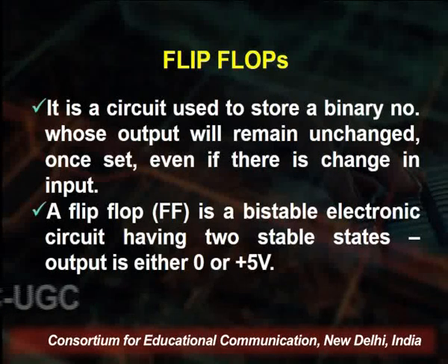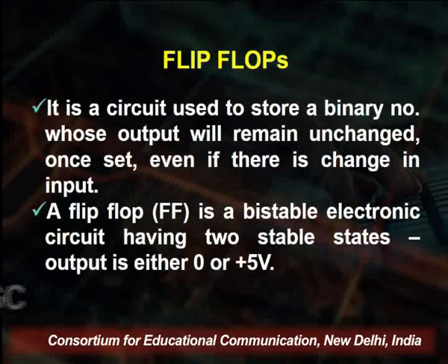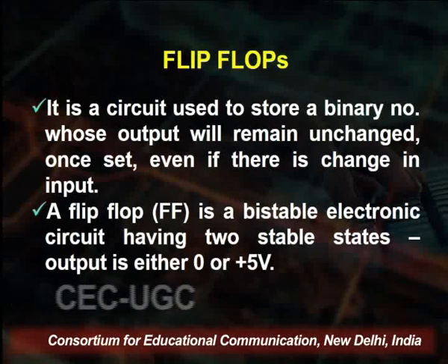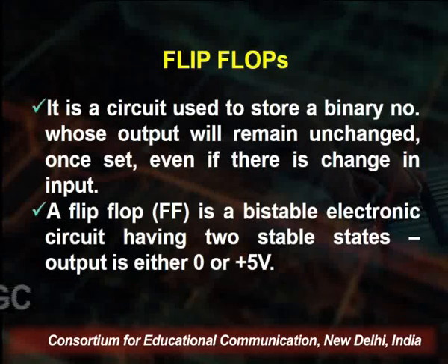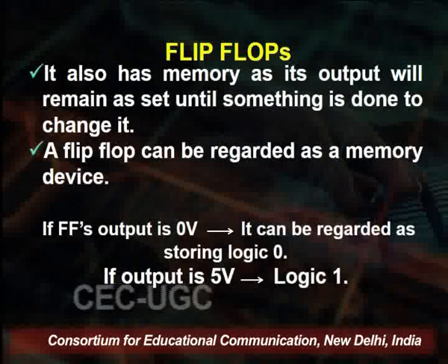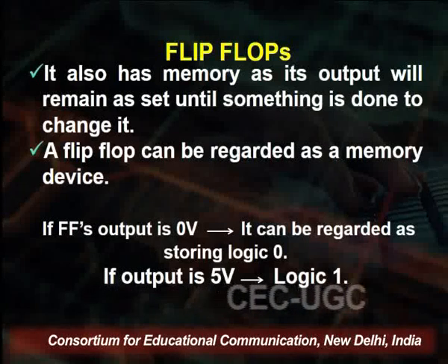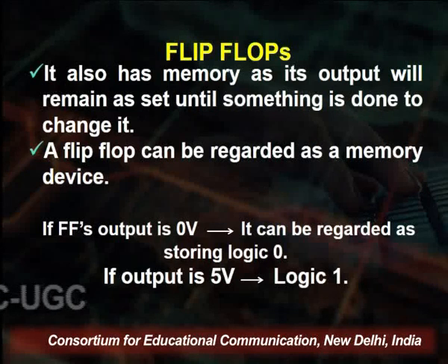Hence, flip-flops are understood to be a bistable electronic circuit having two stable states, where the output in analog terms can either be 0 or 5 volt, while in digital terms it can be 0 or 1. They serve as a memory because until and unless we make an intentional change, they retain the last state. The last state could be a 0 or a 1, and hence the flip-flop behaves as a memory device.